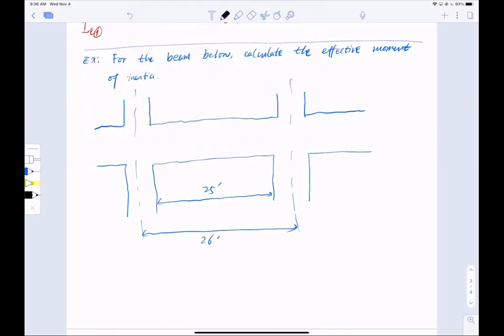Now, in the middle span here, it is going to be positive bending moment. So I know the reinforcement is going to be at the bottom. And then I extend my reinforcement across it, so I have more bond development length. We'll talk about that next lecture. But that's my main tensile reinforcement, and these are two number 8 bars. This is a side view, so you don't see the other one in the outside plane direction, but this is two number 8 bars.